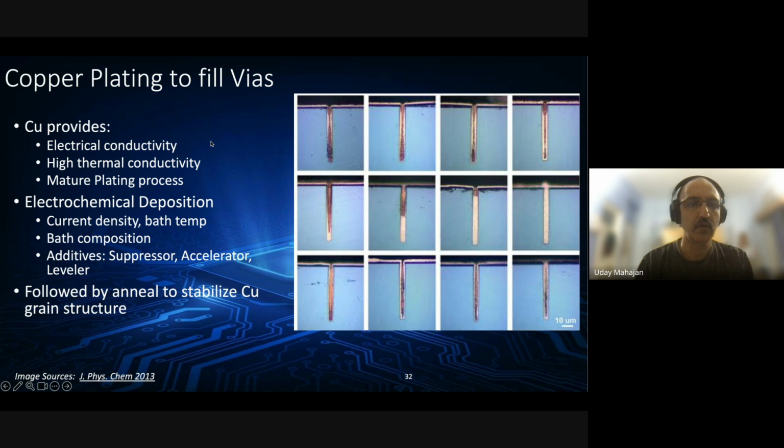The accelerator accelerates the filling or plating of TSVs from the bottom, gives you a bottom-up fill, as you can see here in the middle. This is exactly what is desired. The fill has to start at the bottom and go all the way up, while minimizing the amount that we deposit on the sides, especially on the edges, so that you don't end up forming seams or voids or pinching off, as we say, the TSV.